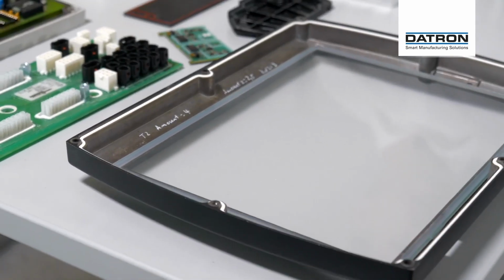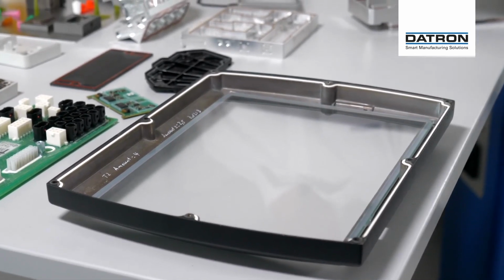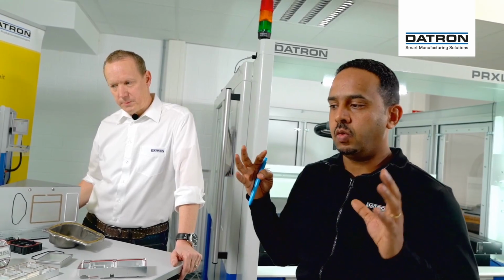With this kind of technology we have 2 advantages. One is the glue of 2 materials, which is glass and aluminum, and the second is the sealing effect. When it's glued, you have directly a sealing effect with the material, with the silicone, so that you have a high IP classification for that purpose, like protection from dust or water or fluids for the electronic cover.